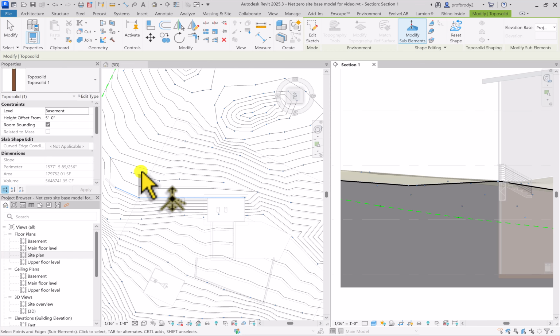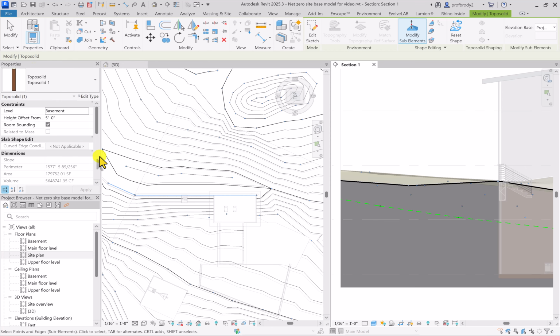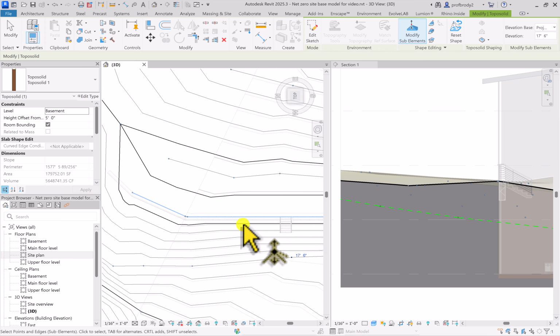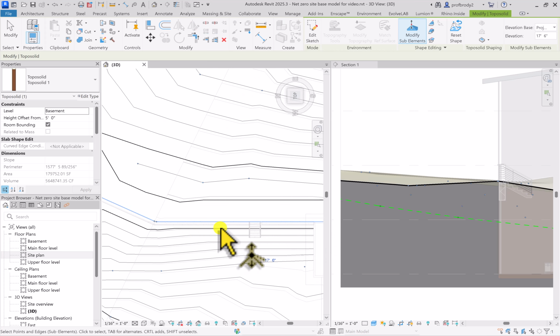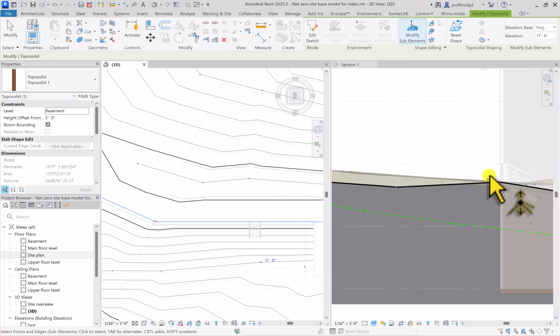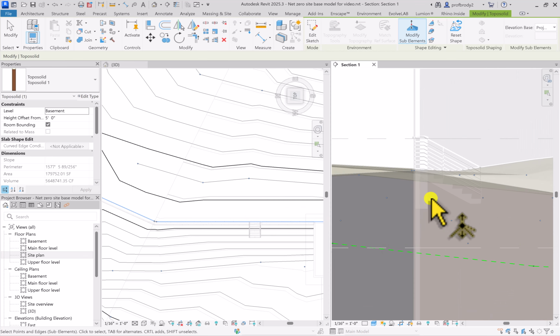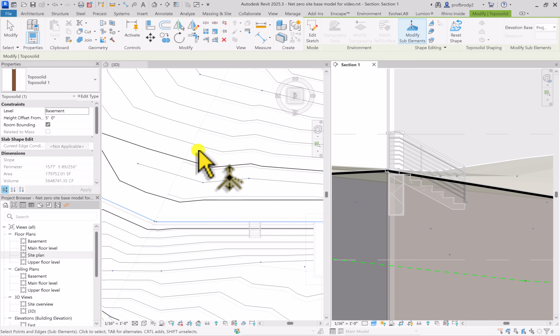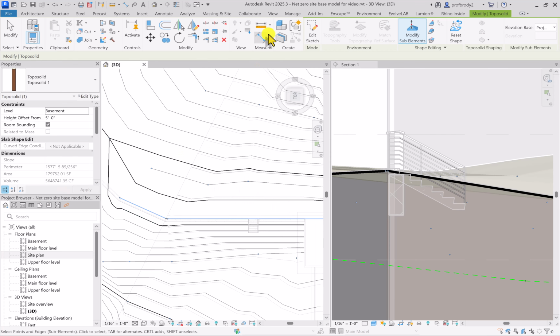So using a combination of the split lines, I can modify the height behind the wall. Now, what about on the other side? Well, if I remember correctly, this was, what, 17 foot 6? Okay, so maybe I'll make the base of the wall have a site height of about 18 feet. And again, I'm kind of doing this rounded, but it's the same process.